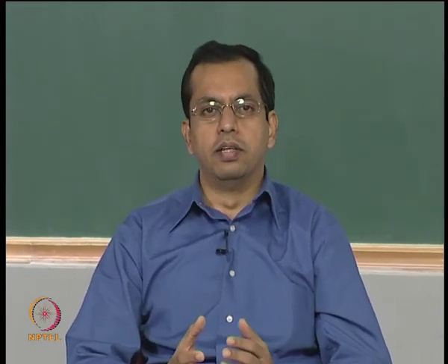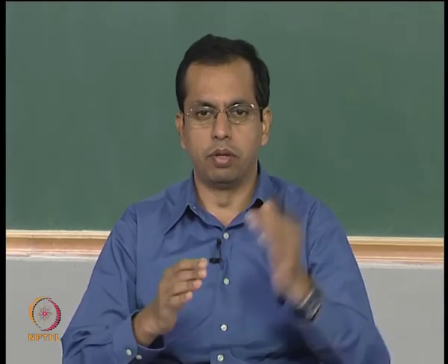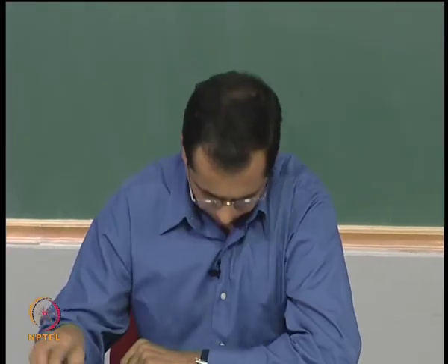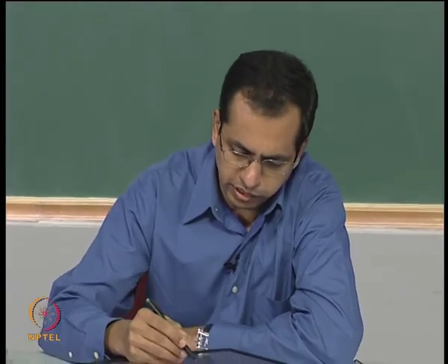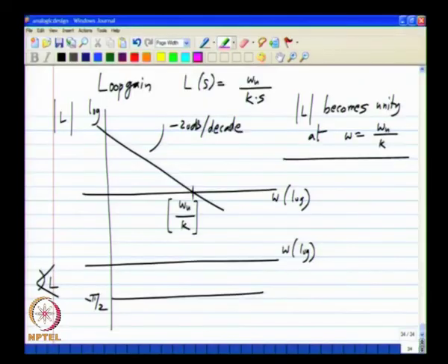Like I said earlier, we are talking about negative feedback loops. That means that something has to be fed back in the loop. You apply something here and then something comes back in the loop. What comes back is described by the loop gain. To have a negative feedback loop, it is not enough to have a connection back from the output to the input. A significant amount of feedback signal has to be there. So what this loop gain signifies is the quantity of the feedback that is there.